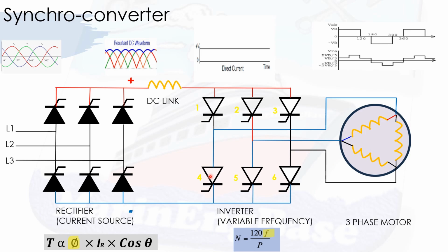But for the inverter bridge, as the supply is a DC source, commutation happens using the back EMF of the connected load, here the back EMF of the motor. So there should be sufficient back EMF available, which makes the current through the SCR fall below its holding current. To make that happen, normally we have to run this motor at 0.9 leading power factor. So, let's say at low loads, about 10% load, there will not be sufficient back EMF produced. Thus, commutation of the SCR will not take place. The SCR will not turn off, or it will not come to a stop.